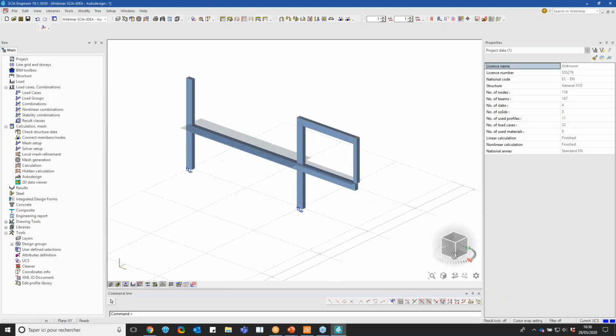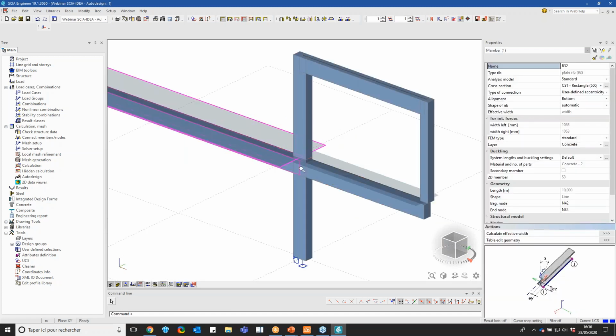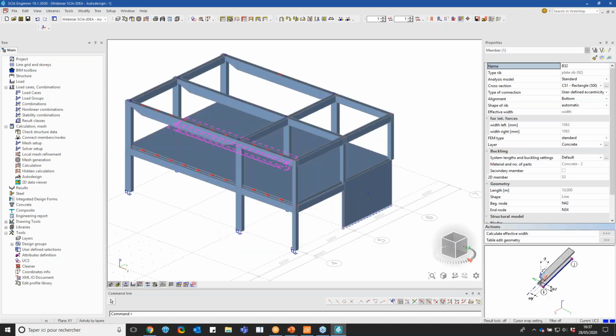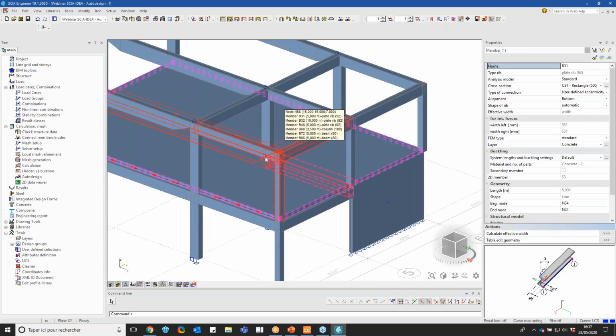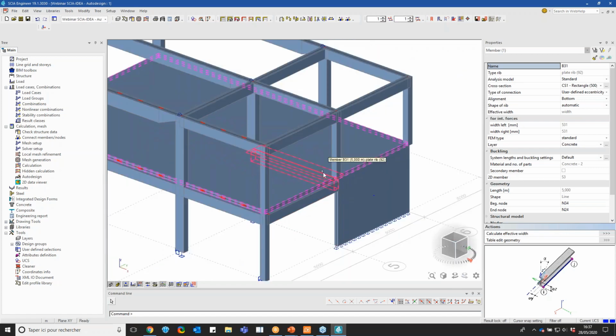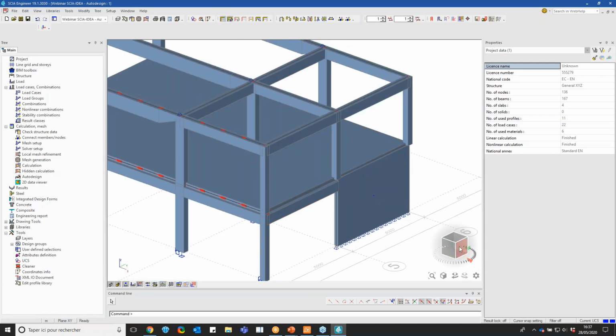As you can see, you can either work in SCIA with 1D elements, so implement your reinforcement as a rectangular section, or also as a T section. So as here we have a concrete deck as well, we can ask to perform the analysis, in any case integrating also the efforts of the concrete deck, and we will perform the analysis and the design on the T section. So this is something you can do in SCIA Engineer as well.